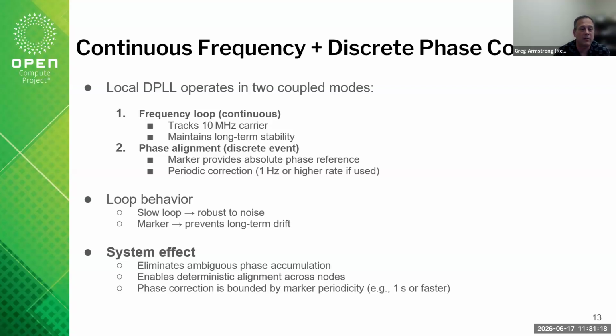So that's the benefit of now distributing frequency, because frequency is continuous, right? You can use concepts like phase lock loops to continuously track that clock. You don't have to worry about, oh, wait a second, and then hope I stabilized long enough in that second to make sure it's exactly at the right time at that edge.